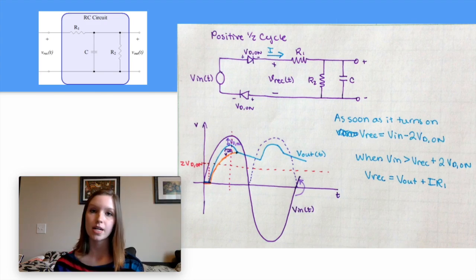The reason that the capacitor decays linearly instead of exponentially in this case is because when we take the Taylor series approximation of the decay, we know that every polynomial of power 2 or greater is going to go to 0, because when you square such a small value, it's going to just get smaller and smaller. So we end up with this line.